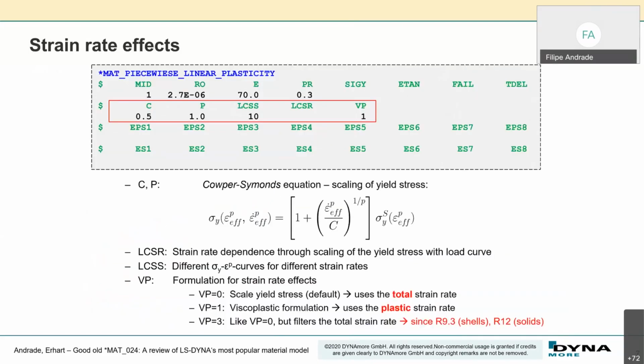Yes. So now, let's talk a little bit about the strain rate effects. There are different ways of doing this in LS-DYNA. There are two things that you have to consider here. One thing is how to introduce the effect of the strain rates, or what is the information about the strain rate effect. And the other thing is, what is the formulation you want to use to consider those effects? So these are two separate things. Sometimes it leads a little bit to confusion. I try to explain here.